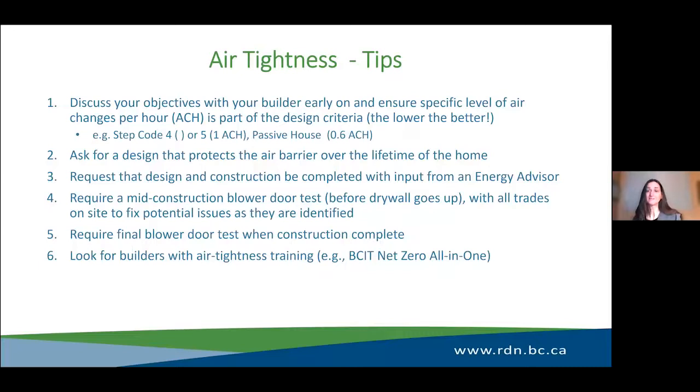And then asking for a design that protects that air barrier over the lifetime of your home is also a good option. One thing I'd recommend is really requiring a mid-construction blower door test. So before the drywall goes up, making sure that there is this air change per hour test that is done, so any issues that exist can be identified when it's really easy to fix them.